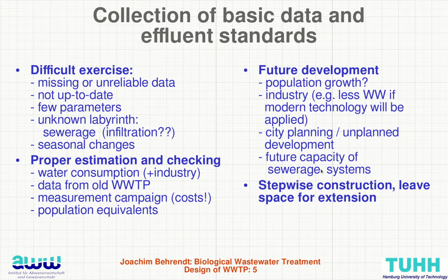And you have to see that there is a capacity of the sewerage systems in the way that it covers future situations. Sometimes if the sewerage system is too big and the time where the water stays in the sewerage system is too long, you have also problems. But finally, if the capacity is too low, then you have also to go ahead. Therefore, a stepwise construction with space left for extensions is a wise approach.